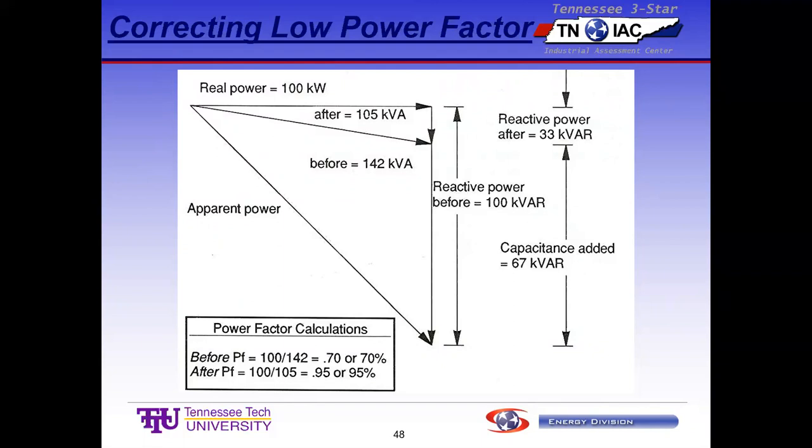Okay, let's get the calculator. What's the power factor going to be in this smaller one? Remember, what's power factor? It's kW over kVA, right? Before, the kVA is 142; on this one, it's 105. So if I take 100 divided by 105, that tells me my power factor.